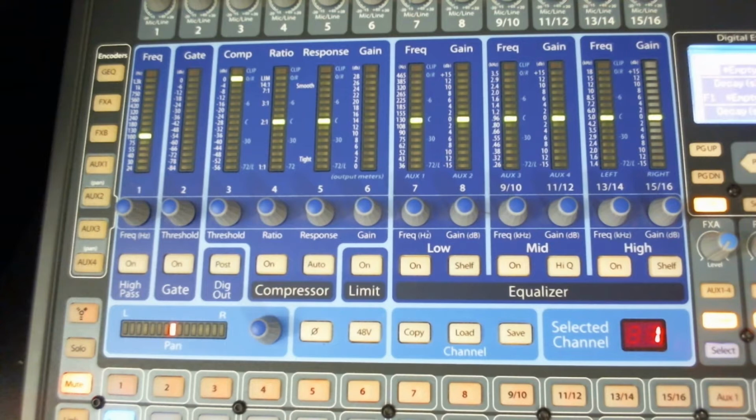So the one other thing that people aren't getting with this board, and you should know about, is the signal flow. The signal comes in through a channel's input, and it's going to hit the Fat Channel. So the first thing it's going to do is come in the Fat Channel and hit this phase switch, because it needs to know how you want to phase the input. If you get a couple mics that are too close, you get what's called phase cancellation. And it sounds funny. It sounds like there's frequencies mixing. It sounds like an old radio or something. If you start hearing that, try hitting this button on the channels that are causing it and see if that doesn't clear it up for you.